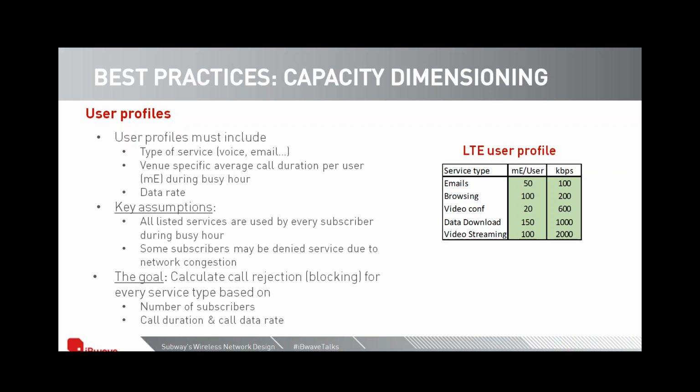It is important to understand that all subscribers at the venue will attempt to place a call of that particular length during busy hour. If I have just completed checking my email, and spent the duration equivalent of 50 milliErlangs doing so, which is close to 3 minutes, if memory serves me well, then I'm free to try browsing next, and then after that video conferencing, data download and video streaming. So all of those services will be attempted during busy hour by all subscribers.